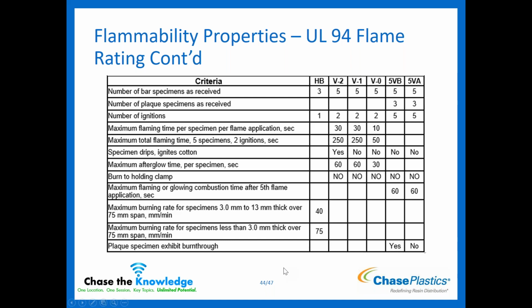And then if you're looking at specifically your Ultem data sheet, you can see the flame rating under flammability. It's got a V2, a V0, and 5VA rating. The other thing to also consider is when you do these ratings, they're based on thickness. So in this particular case specifically, at 0.4 millimeters, my Ultem is a V2 rated material, and so it's going to perform not as well as when it's 0.75 millimeters. So that's going to be a V0.